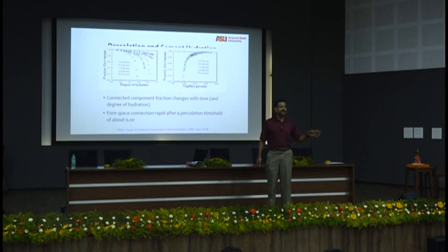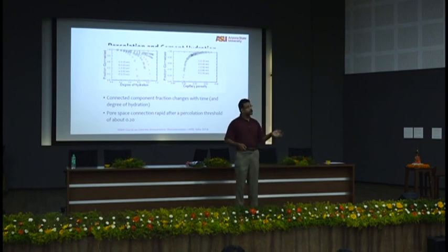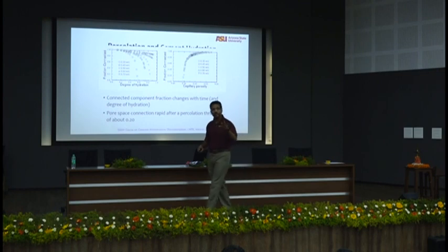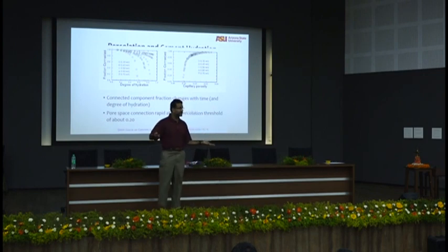Try not to say that I'll give you a concrete with a porosity of 10%. Okay, you might get it with a water cement ratio of 0.2 and with large amounts of admixtures and cement not hydrated. But it's not required for general purpose concretes. For general purpose concretes, what you want is a connected solid system, and 20% porosity where the solid system is connected and the pore is not connected. So what? Leave it at that.